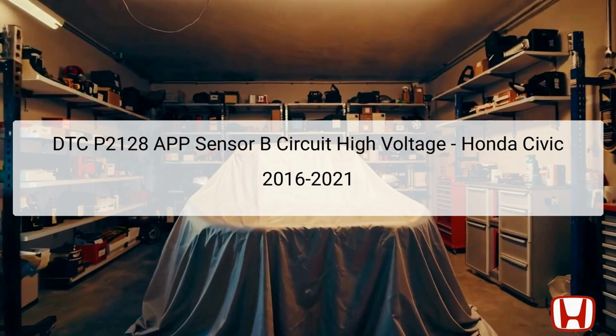The DTC P2128 indicates a problem with the APP (Accelerator Pedal Position) Sensor B, specifically labeled as TP (Throttle Position) Sensor E. This error suggests that the APP Sensor B is reporting a high voltage within its circuit, which may lead to erratic engine performance or throttle response issues.